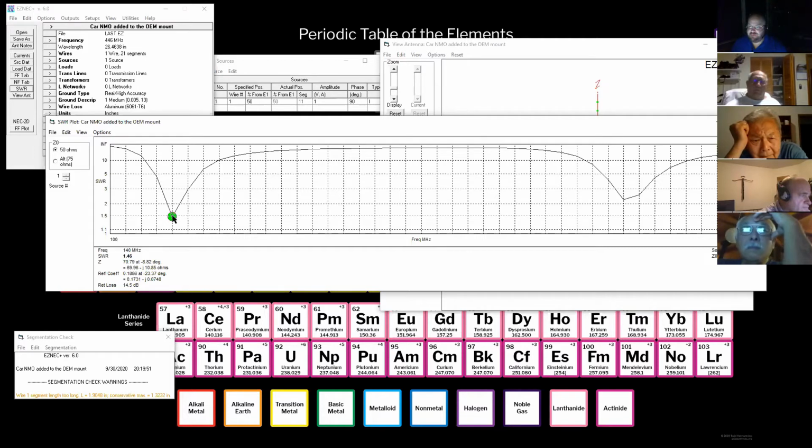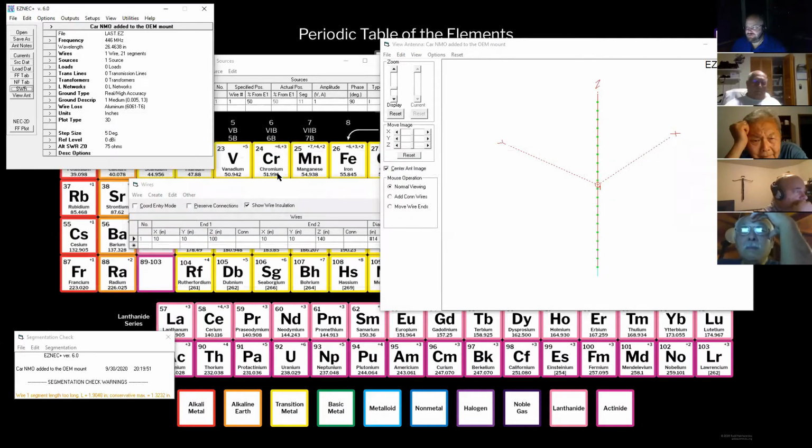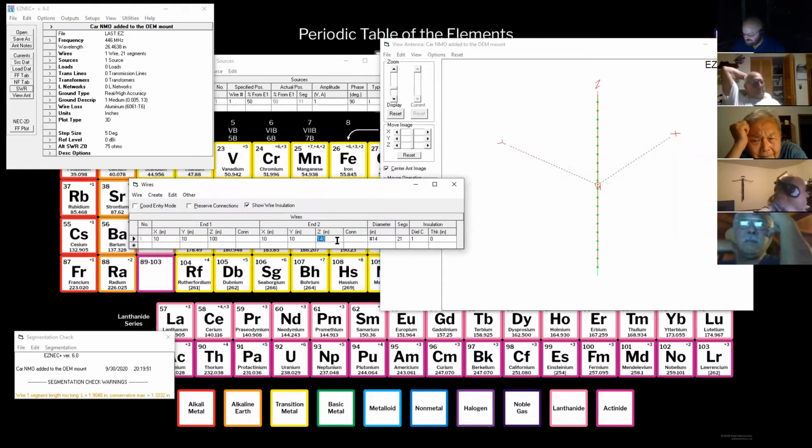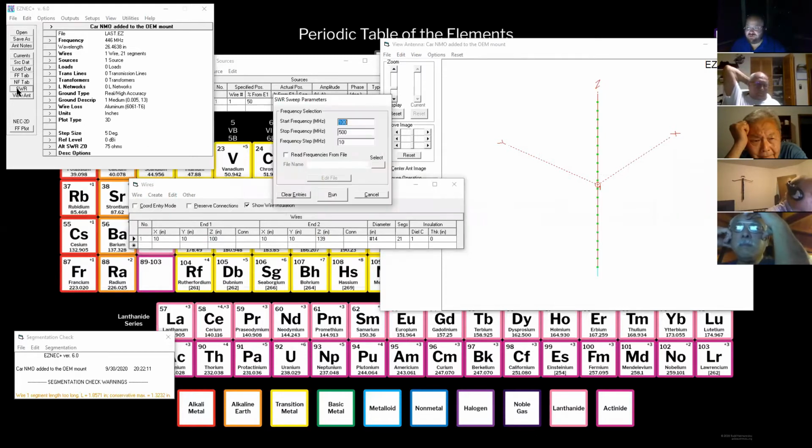So for the ham band, I'm not exactly where I want to be. I can already tell that. So let's just shorten this wire up an inch. And what I did is, these are Z calculations. I started my wire at 100 inches above the ground, and I was at 140 for the top. Now I'm 139. It's an inch shorter. So now if I run this again,